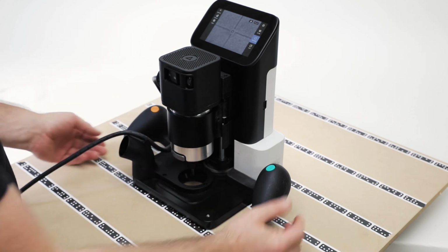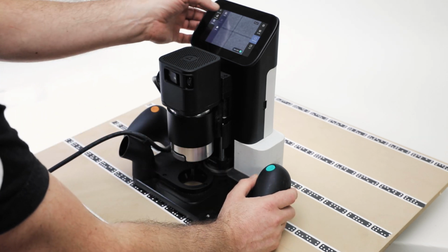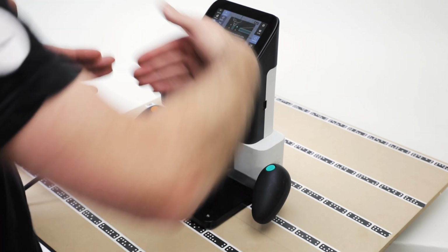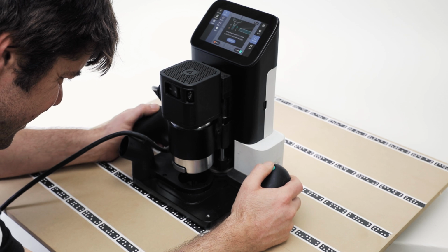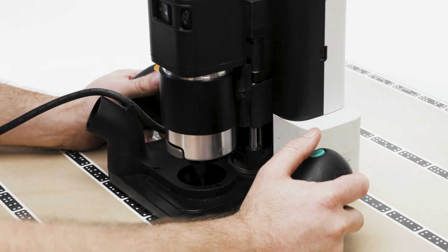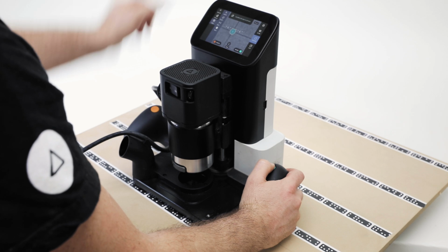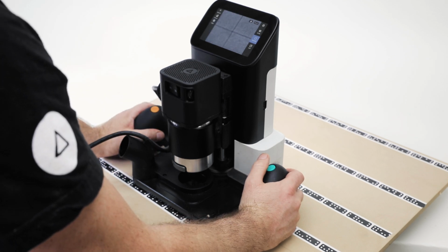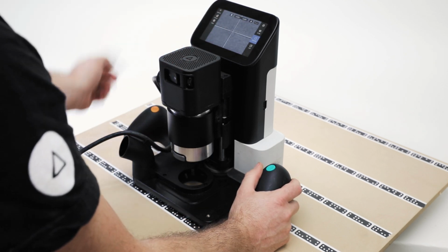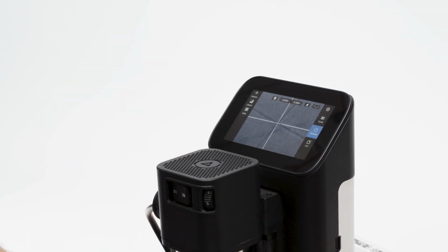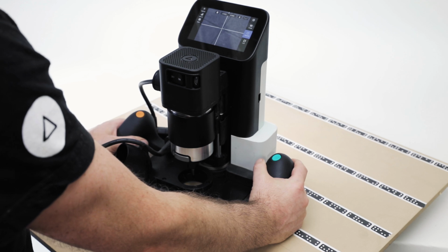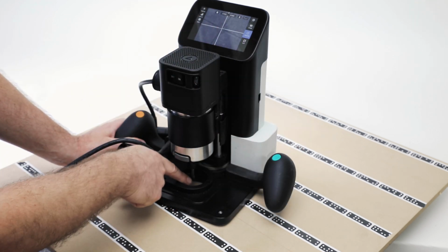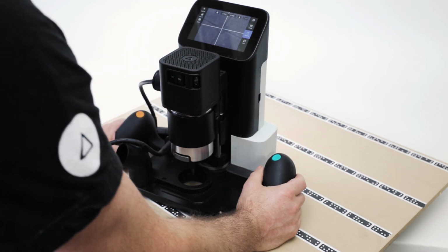So I'm going to do the same as I did in the previous one. Use an engraving cutter, lower it down until I'm satisfied that it aligns perfectly with a point down there, my pencil mark. Then I just hold everything still, double click the green button, and I get a grid that the 0 point is exactly that point I referenced, and it's oriented relative to Origin. So I mean, that makes sense if you say just want to quickly place a circle or something like that. Something that the orientation doesn't matter, but the position is important.